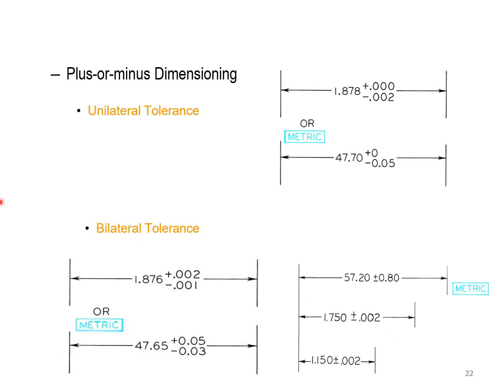So we have the plus-minus method, which is for the neutral tolerances. You can write down that the dimension is 1.87 inches plus 0 above and minus 2/1000 below. Or in metric, we can say that the diameter is 47.7 plus 0 minus 0.05. So that's the tolerance we can have for the dimensions. We can also use the bilateral tolerances, where, unlike the unilateral, we simply write it as plus-minus as one figure. Here they don't allow a larger maximum size, but they allow a lower size.